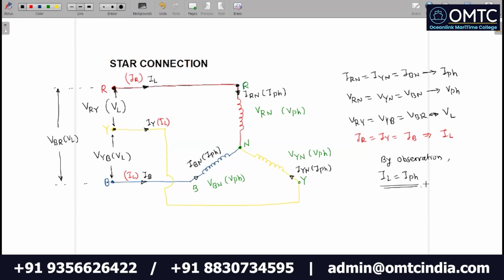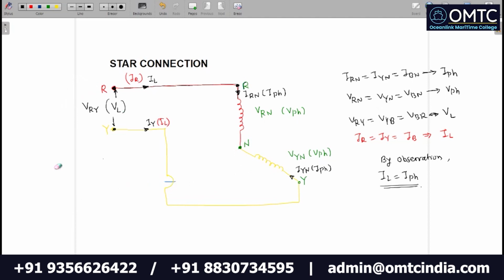What about line voltage and phase voltage? What is the relation between line voltage and phase voltage? Let us consider one line voltage here, that is voltage from red line to yellow line. I am removing the third winding here to understand the relation between phase voltage and line voltage. This is now a complete circuit. By Kirchhoff's law, I can write VRY, this voltage, is equal to the sum of VRN plus VNY.